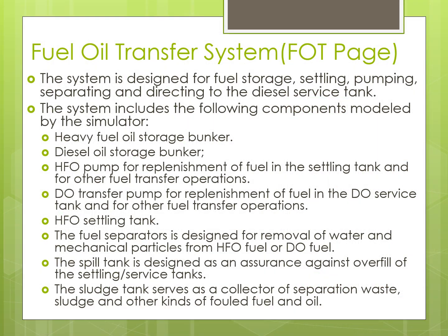Fuel oil transfer system. The system is designed for fuel storage, settling, pumping, separating and directing to the diesel service tank. The system includes the following components modeled by the simulator: heavy fuel oil storage bunker, diesel oil storage bunker, HFO pump for replenishment of fuel in the settling tank and for other fuel transfer operations, DO transfer pump for replenishment of fuel in the DO service tank and for other fuel transfer operations.